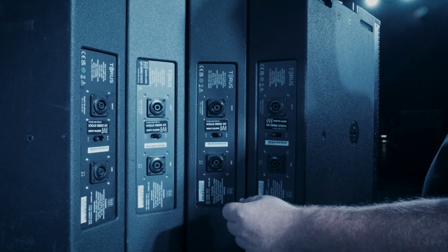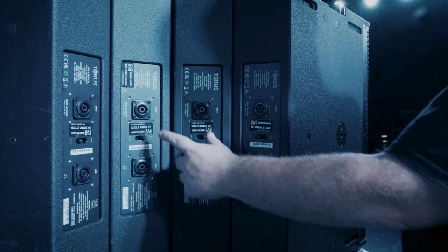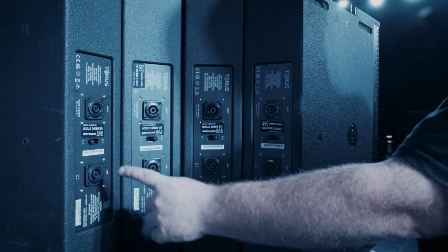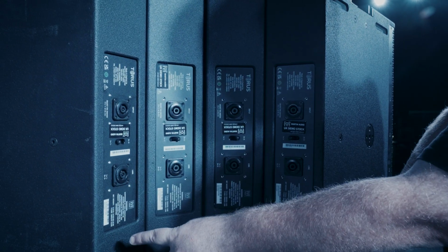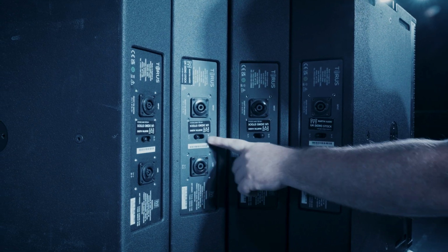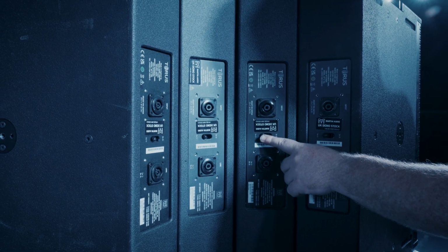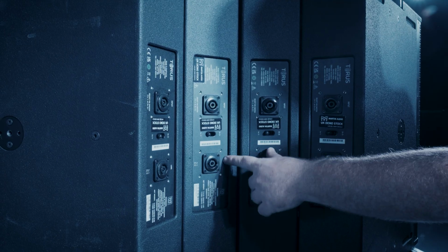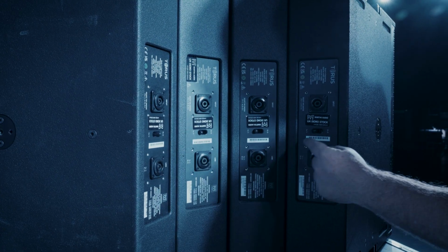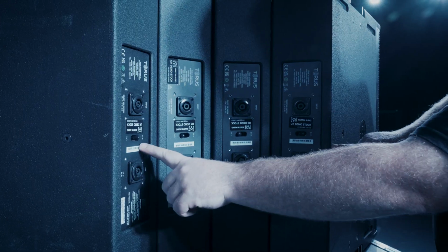A common deployment when building horizontal arrays is to pair cabinets in parallel at 2-box resolution from the centre out, with circuit 1 on the inside pair and circuit 2 on the outside pair. The centre pair will be allocated to pins +/-1 and the outside pair allocated to pins +/-2, with amplifier circuits increased for every pair of loudspeakers required for coverage.